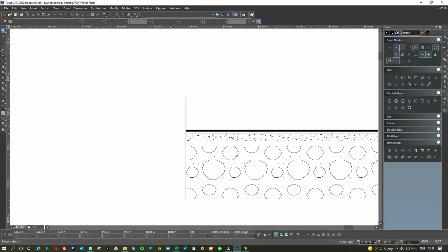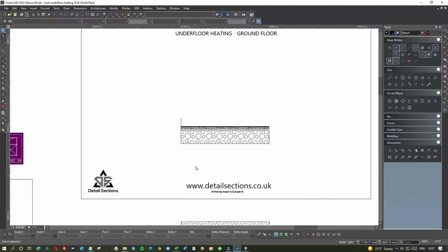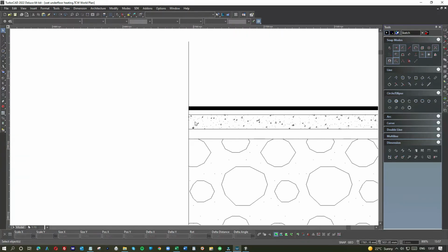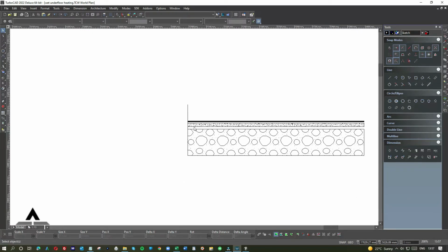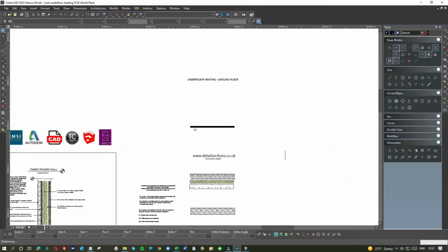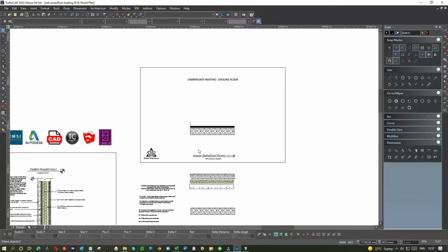So again, hardcore, rubble, soft sand, blind it to get it nice and level, DPC on top, and after that, incidentally, the DPC actually goes up the walls. If there was a wall there, it would go up the wall, so that you're basically going to cocoon the insulation.